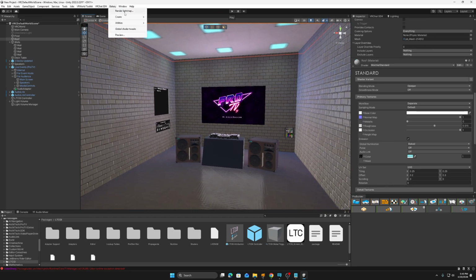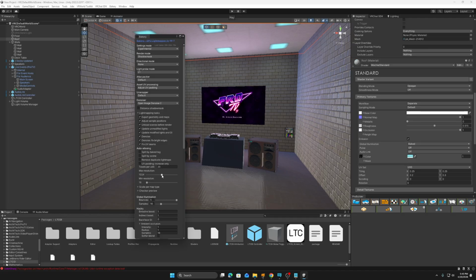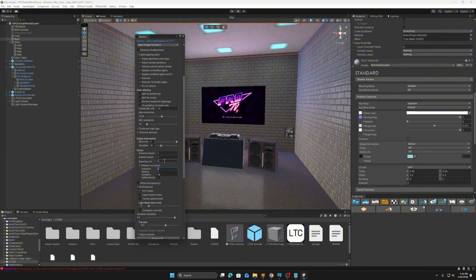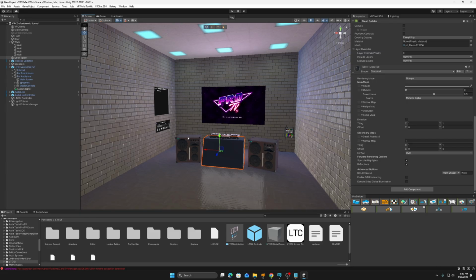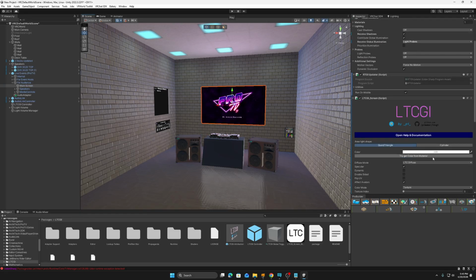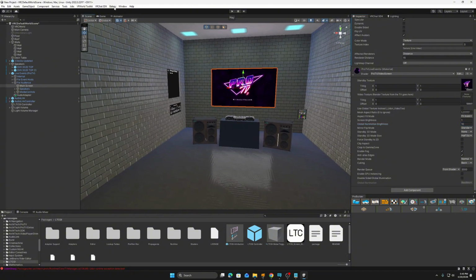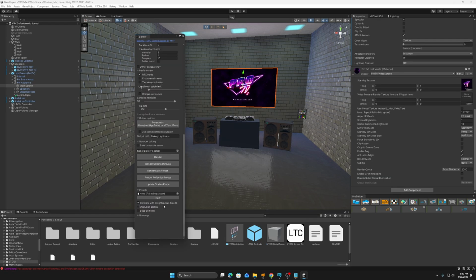So we'll go Bakery, render. And now we'll do a basic resolution still, but we'll do an intensity of the emission boost of 1.5. And we'll do an ambient occlusion of 2 for a little better shadows there. And we're going to reduce the screen brightness by, let's put it at 15 for now. Actually, just 10. It'll make more sense. All right, so we'll go render and render again. Save.